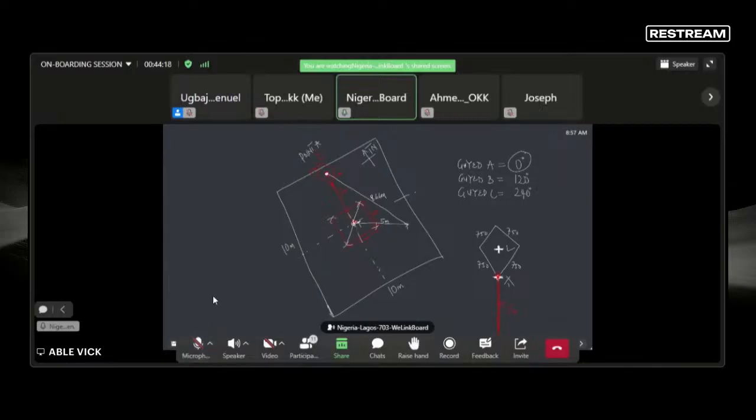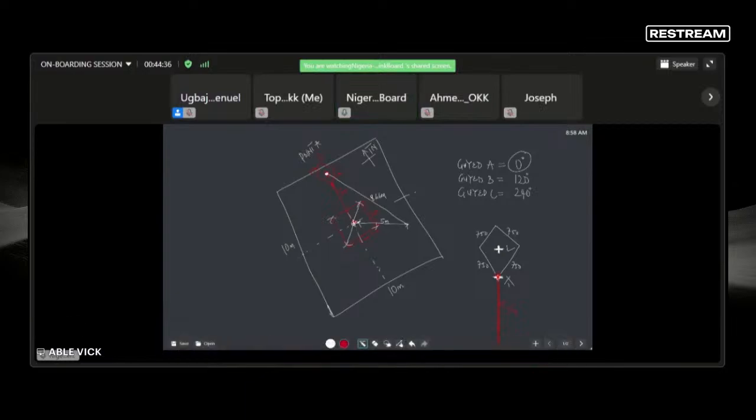That exact point. It means on that point, you should be seeing 8.66 on one tape and 5 meter on the second tape. Where the two tapes meet is your guide wire at point B. And that midpoint, that point is the middle of the base plate. So at that middle, you need to now set out your guide wire base plate.